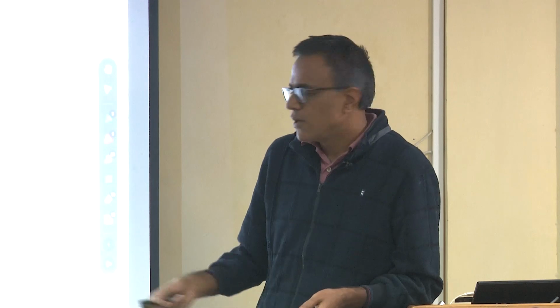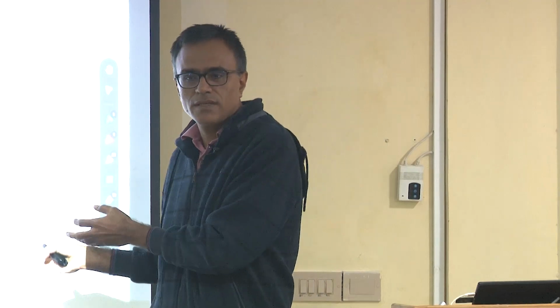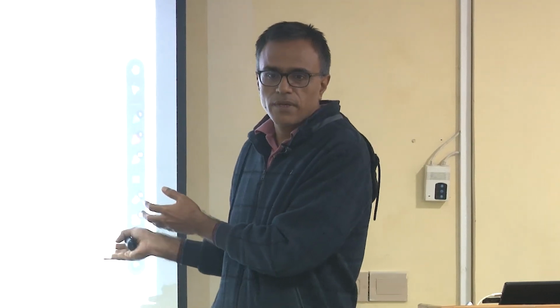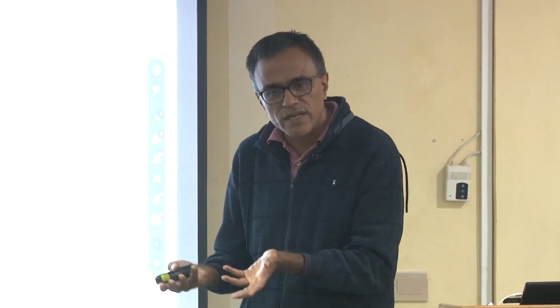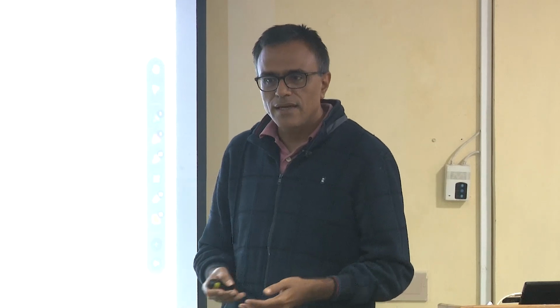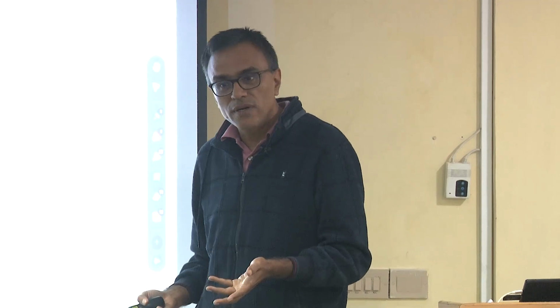So what has it fed back? PMI, RI and MCS in both the cases, whatever is the rank. Do the same operation for all other precoders, for all other configurations, right? If it is rank 3, 4, 5, 6, 7, 8, up to 8, it can go. Who is going to tell that? UE is only going to tell that, right?